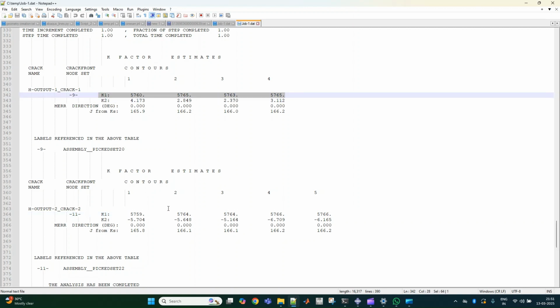If we go to the closed form solution, we can calculate, we may find it is less. And from our intuition also, edge crack is more dangerous than the inside crack. So edge crack is more dangerous, the SIF is more there. Here the SIF is considerably less. It will be like 10% less or so. So this is how we have done the calculation.